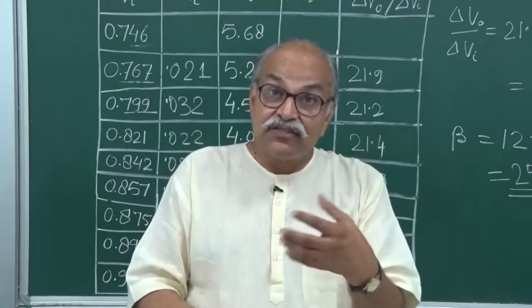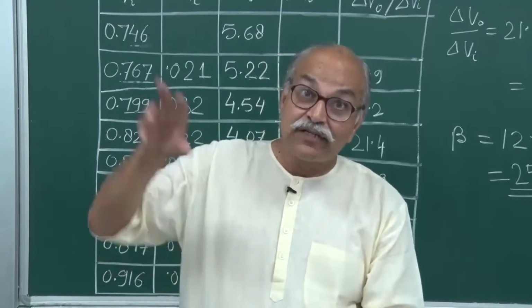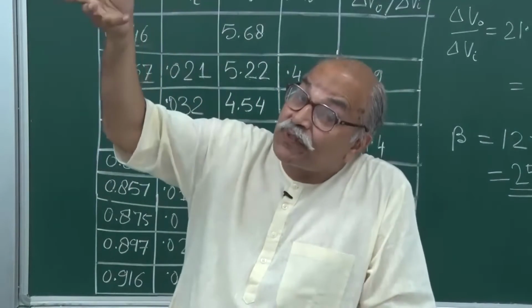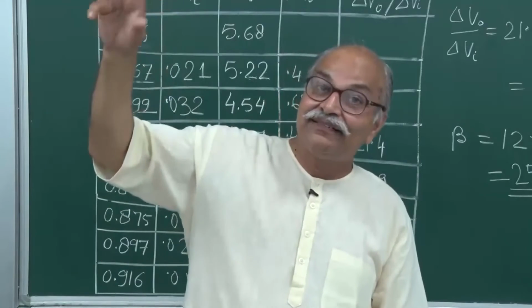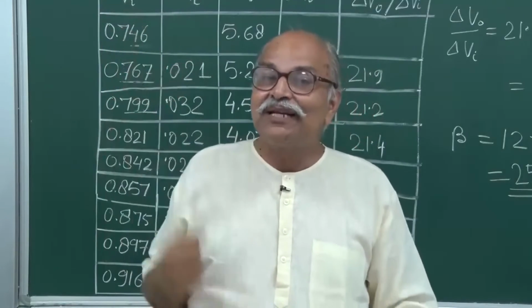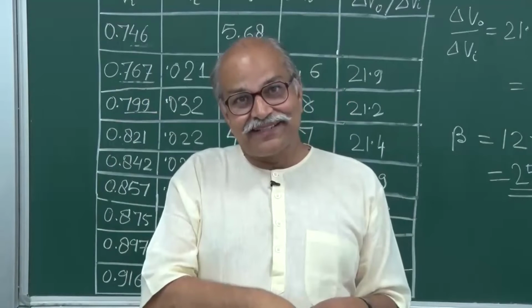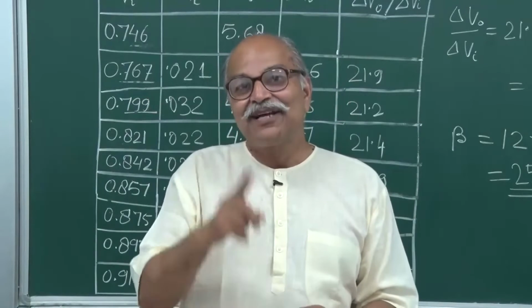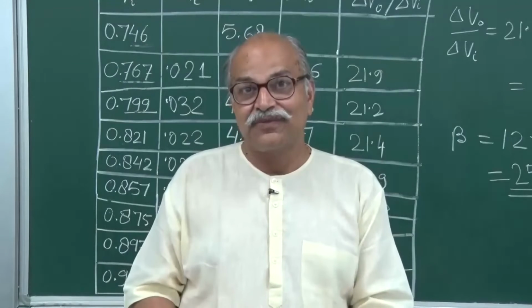That is the switching. So you are switching in the base circuit, and what we are controlling is the output. You are doing something here and the result is appearing there. So you are controlling a high current circuit from a low current circuit, and that is the benefit. That is how the switching takes place, and that is why the transistor is used for switching.